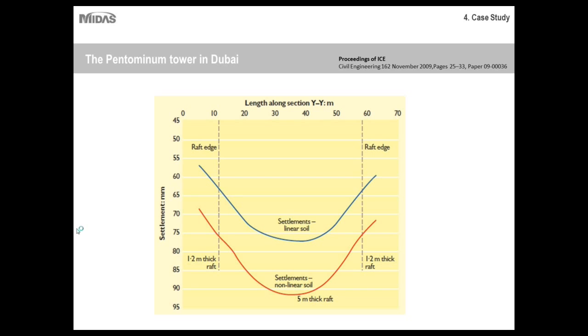That's one of the main things I want you guys to get from this presentation in general: that through numerical modeling you'll be able to find more cost-effective solutions. For larger scale projects, it becomes more and more important to take design costs into account. For example, by cutting down the number of piles or using a certain type of element over another, you could save hundreds of thousands of dollars just because you took the time to do a parametric study instead of going with a more conservative design. So keep in mind that numerical modeling is useful not only in the physical sense of calculating your results, but also in the economic sense.